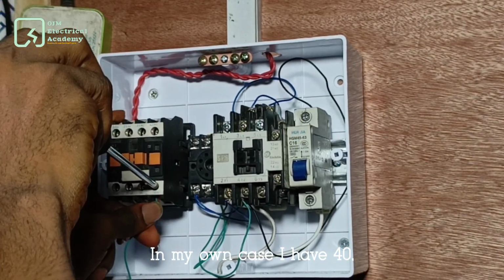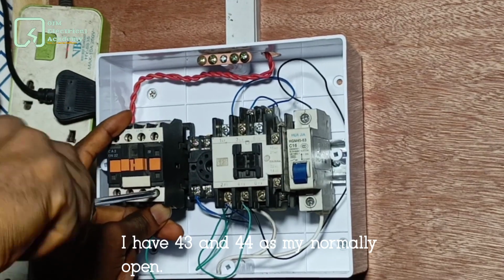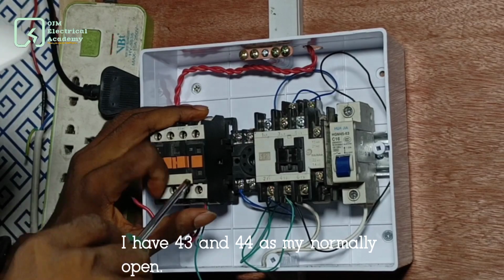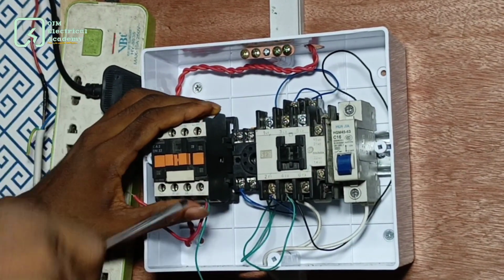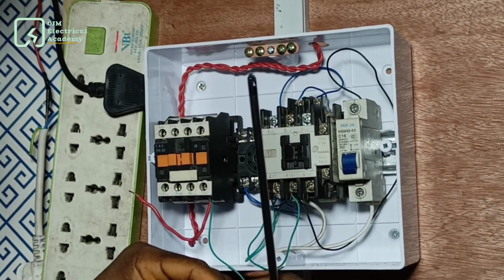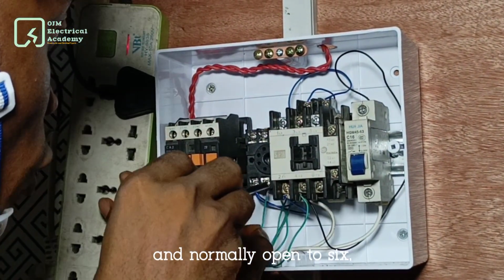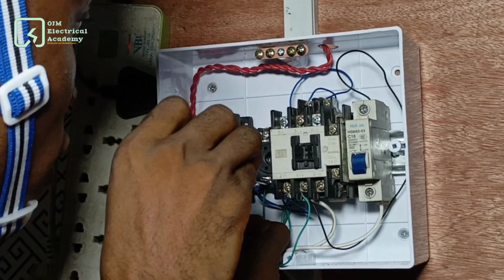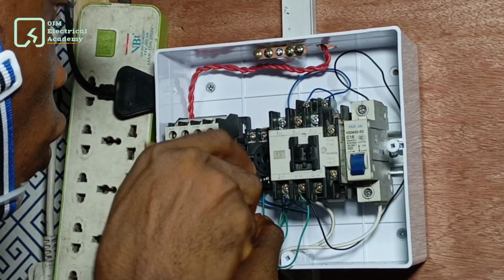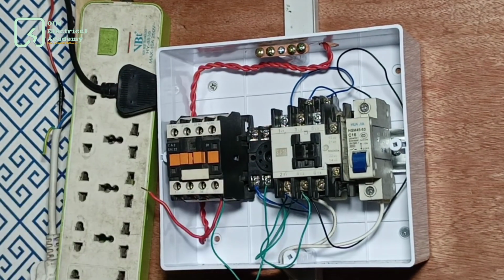In my own case, I have 43 and 44 as my normally open. So it will go from here to the terminal number 8, which is common, with normally closed to 5 and normally open to 6.